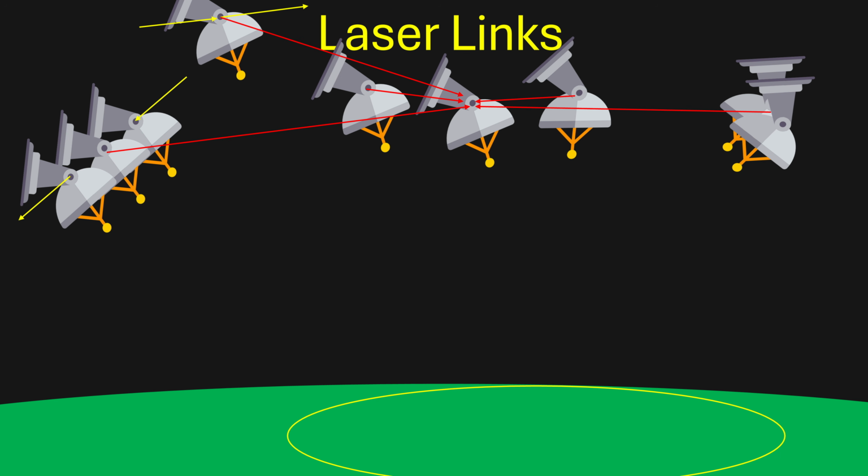The obvious solution for this is laser links. Because these use carrier frequencies in the hundreds of terahertz, you can have a very high bandwidth signal that will give you very precise ranging. This will also have the bandwidth needed to pass raw antenna data between the distributed satellites and the central satellite. The phase errors introduced from using different demodulation electronics on each satellite would be a much more serious problem, but it's plausible that this can be solved as well.